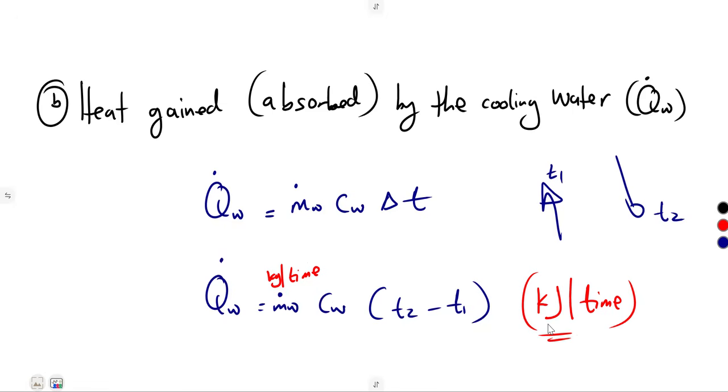So we have the mass flow rate, and the specific heat capacity of water, which will be given in kilojoules per kilogram degrees Celsius, or they can use Kelvin there. There is no effect. Don't change anything, just use it as it is. And when it is not given, you use the value 4.187.